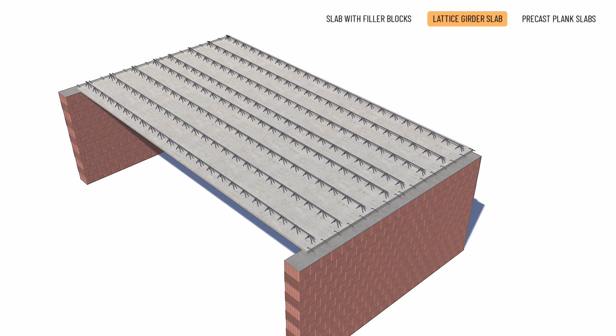These panels are not mass-produced, but unique prefabricated products, with a typical width of either 1.20 or 2.40 meters. If the reinforcement is custom calculated, it can span 10 to 12 meters of wall spacing. The main advantage of this system is that the slab does not require any formworks, and the elements can be quickly lifted in place by crane.